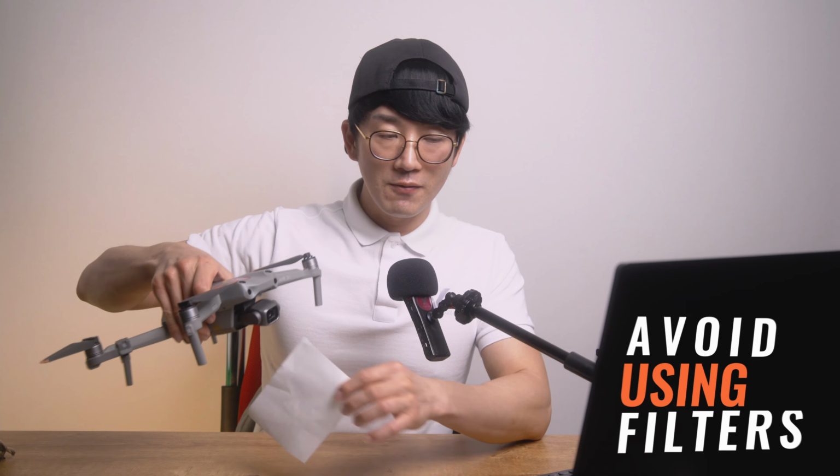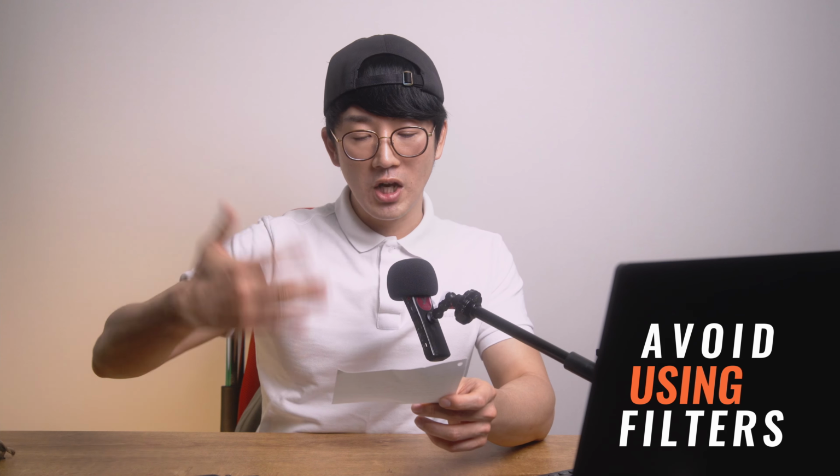Of course, before you press the button, always check the mission settings, altitude, and gimbal pitch. Double check. And of course, we are dealing with photos, so I don't think it's a good idea to use ND filters. I don't want to block anything except when I do videos. When I do photos, I don't want to use the ND filters or the CPL filters.